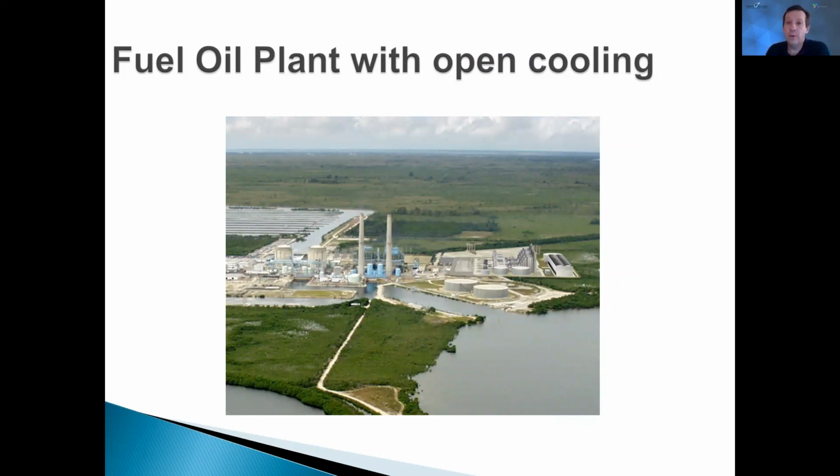Likewise, even in the cooling towers, they don't want to get those things dirty because they have to use chemicals to clean them up. And the oil is a food source for algae. Cooling towers are monitored for algae as well, because algae blooms in cooling towers are very easy. It's a hot water source and there's sunlight, so algae blooms there. Biocides are expensive, so if you know you have oil, you can control your consumption of chemicals.